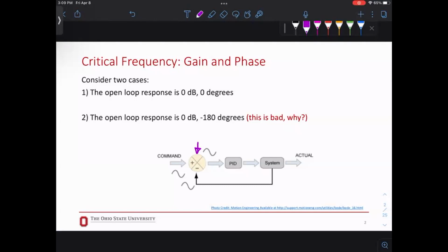So our system on its own might not be unstable. When we design a controller, we might create that phase shift from the output with the input, so that the controller sees an excess error that doesn't actually exist. So when we are looking at the Bode plot, we are going to look at that negative 180-degree phase shift at 0 dB. All right, so we're going to go into more details, but this is one of the points that we want to look at.